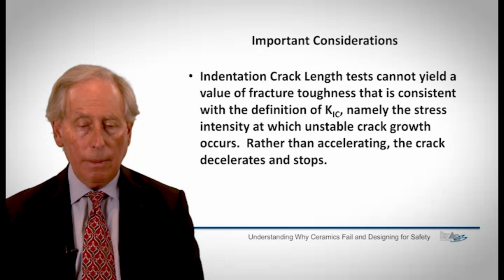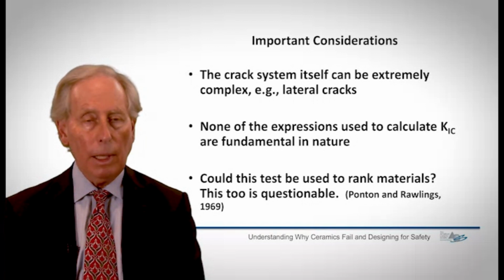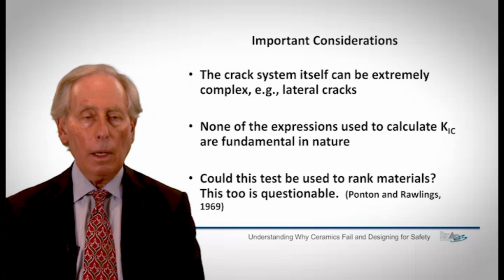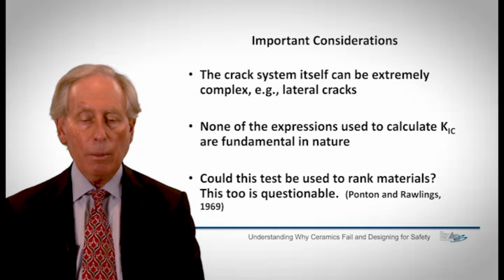In addition, the crack system can be very complex. Any of you who have put hardness indentations into ceramics know that it produces damage at the site. There are what are called lateral cracks, which are parallel to the surface in which I'm putting the indentation rather than perpendicular, which I use to calculate the fracture toughness.